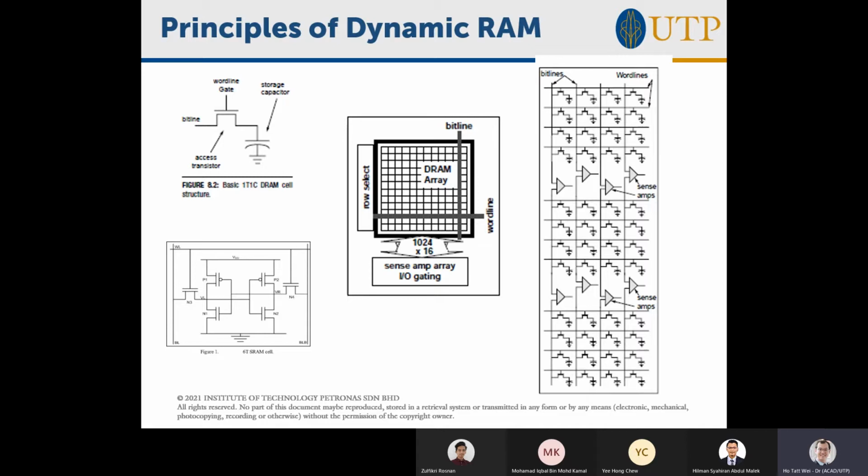Super old, from the 80s, if you talk about TTL at 5 volts, that's bipolar transistors. CMOS, you talk 3.3 volts, that's discrete circuits. Almost no circuit that is expensive and high performance is at 3.3 volts anymore, unless it's very cheap. Most likely you have 2.5 volt CMOS, 1.8 volt CMOS, and 1.1 volt CMOS. The VDD is 1.1 volt, 1.8 volt, or 2.5 volt. So naturally, depending on what the VDD is, that's logic 1.